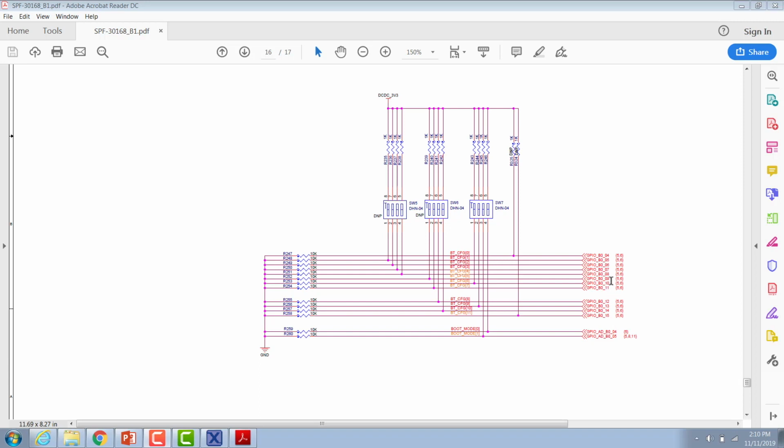Another thing to be careful with when you're using the GPIO overrides, these are sampled at reset. You want to make sure that the circuits that you're using on these pins during regular runtime don't interfere with the boot configuration option. For example, if you're using any of these pins as an I2C, you may have pull-ups enabled on the pins that could potentially conflict with the boot configuration selection. So that is something to look out for in your design.